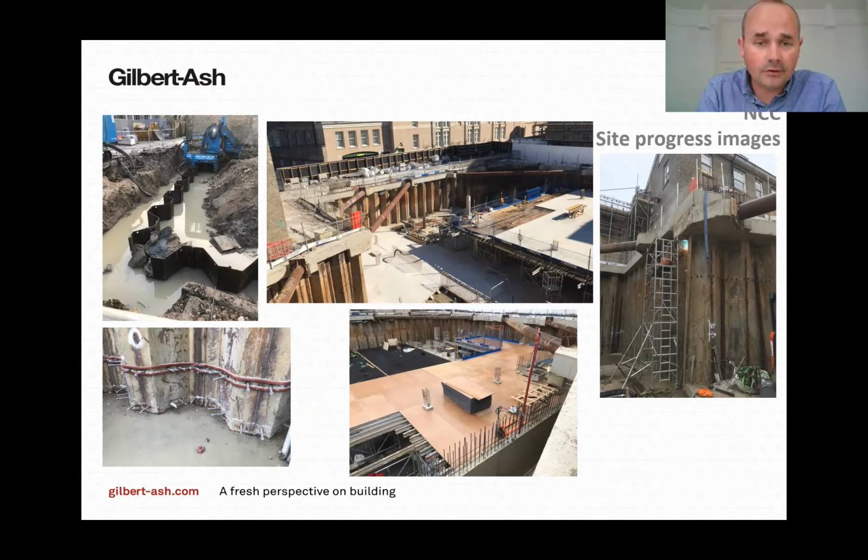And then just going into the middle picture there is probably the most up-to-date photograph we have, our image of the basement and where we currently sit. You can see there that we have completely completed the B2 slab, and we are commencing with the B1 slab, the temporary formwork there erected. You can also see there the size of the propping, the temporary props that we had to introduce for the basement, naturally in its temporary form until the permanent solution is in place.